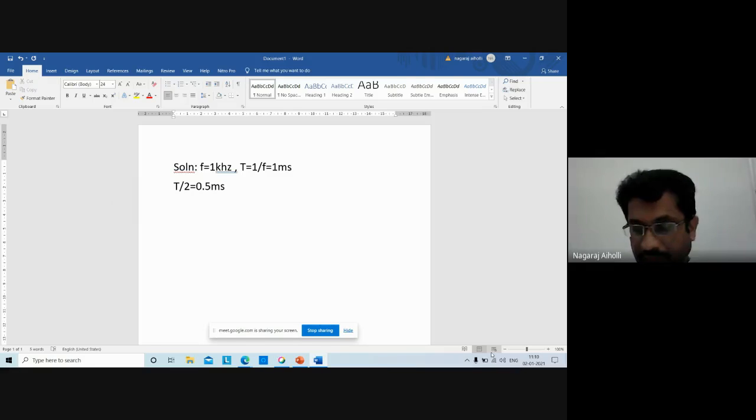Okay. Now here, the starting value that has to be loaded into timer registers TH0 and TL0 is given by T on or T off, the on time or off time, divided by the time period.